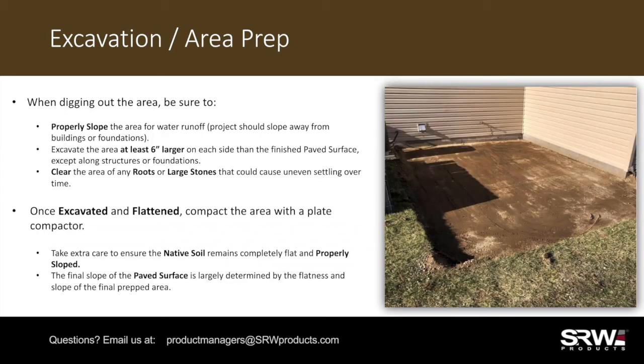When digging out the area, be sure to properly slope the area for water runoff. The finished project should slope away from any buildings or structures. Be sure to excavate the area at least 6 inches larger on each side than the final paved surface, with the exception, of course, for structures or foundations. Lastly, be sure to clear the area of any tree roots or large stones that could cause uneven settling over time.